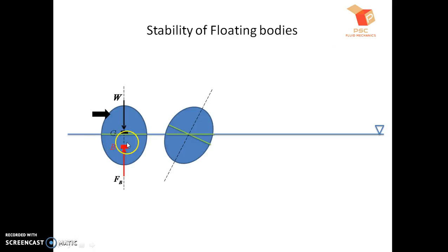But now one key difference we have is, if we consider this body axis, initially on the left and right of this body axis we had the same volume, because of which the centroid was somewhere here. But now when we see this body axis, on the left part of it we have less volume, whereas on the right part of it the volume is larger, because of which the centroid will now get shifted in the rightward direction. So the centroid will not be here like before, it will get shifted to the right and take some new location.